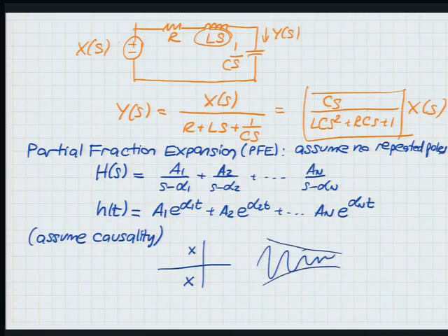That's not the best drawing, but I hope you're understanding. If I have a single pole, what is the response? Just an exponential decay, right? So that's why we get a lot of intuition. For example, whether or not the poles are complex will determine whether you'll see oscillations in your system response, right? So, very critical information, right?